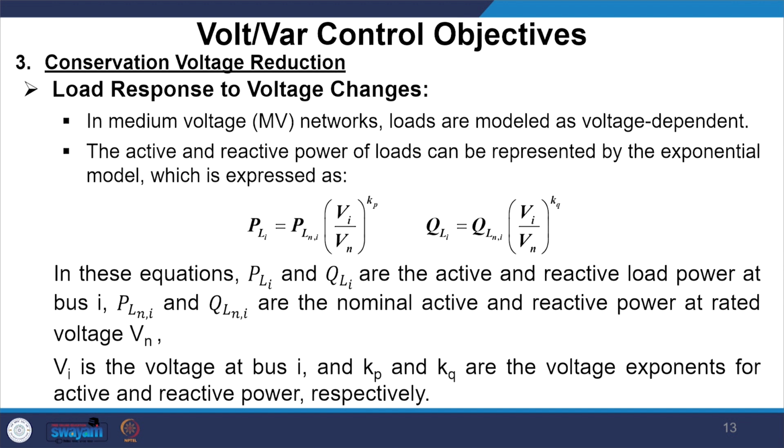The active and reactive power of load can be represented by the exponential model, which is expressed as P_Li equals P_LN times (V_i upon V_n) to the power Kp. So this is my real power load model, and this is my reactive power load model, where Q_Li equals Q_LN times (V_i upon V_n) to the power Kq.